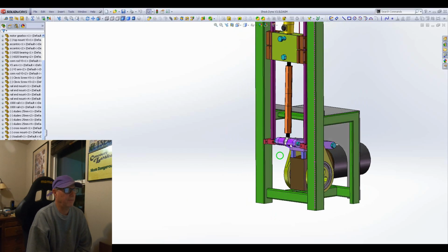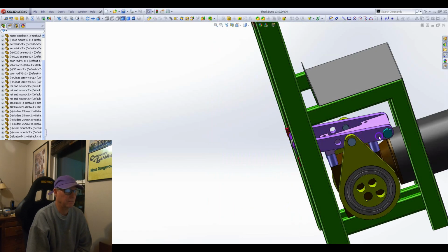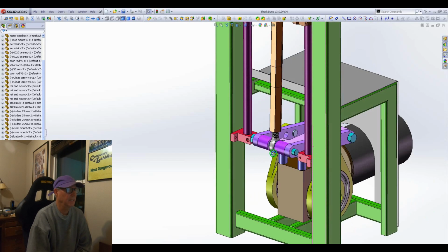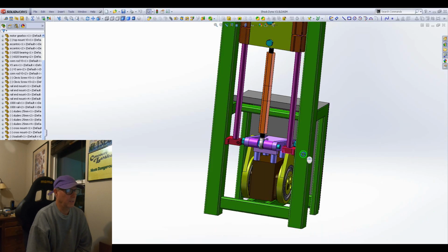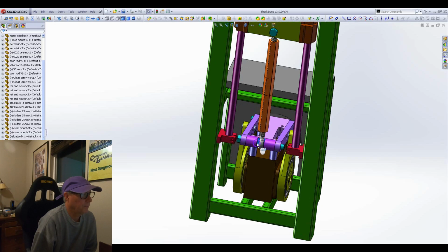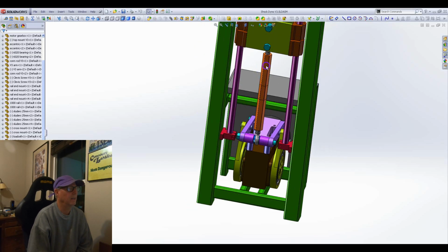As you can see, I significantly simplified the A-arm. The A-arm is basically just a piece of steel with some holes drilled in it and rounded edges. This piece and this piece are separate pieces, so I don't have to worry about getting that perfectly perpendicular. And then this just has a through bolt and a heim joint on this rod here.